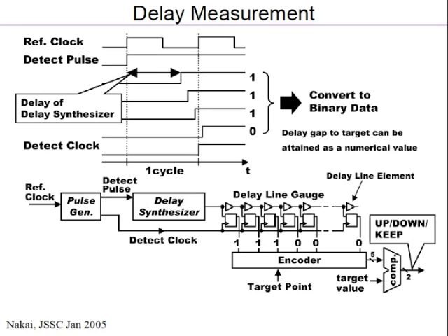That is up to you as a designer. You can say 3 additional buffers. I will adjust my supply voltage such that when I make a delay measurement, my edge has propagated beyond this at least 3 buffers. It could be more, which is okay. But if it's 2 more, then that means my voltage is too high. I keep reducing the voltage such that I reach my delay of the synthesizer plus 3 buffers. Right? So that is basically how you set up the control loop.